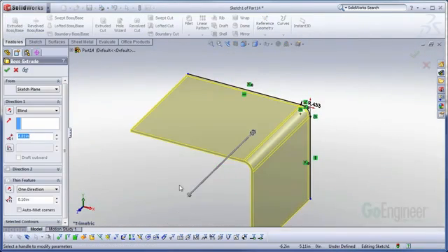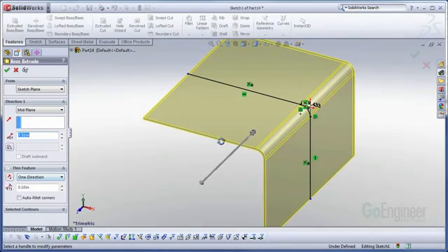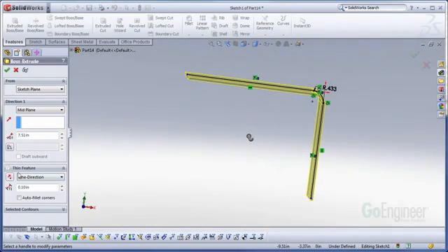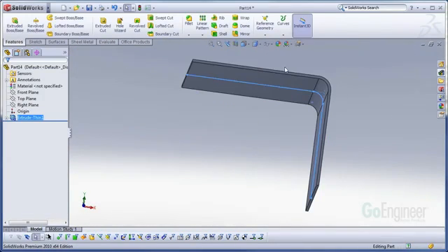And now my geometry is going to be constructed onto this, so I'm going to create just a boss extrusion. Let's go ahead and make it a mid-plane. Pull it out a little more for a little more space to work with, and it's going to have the thickness be directed outward. So I'm working on that 11 millimeter radius to create my forming tool.